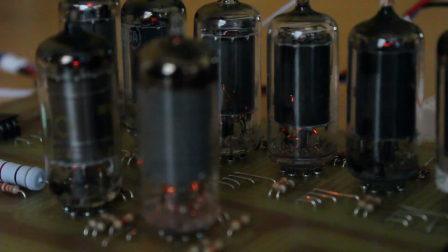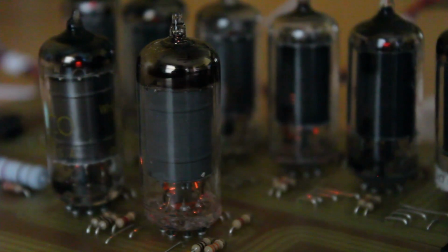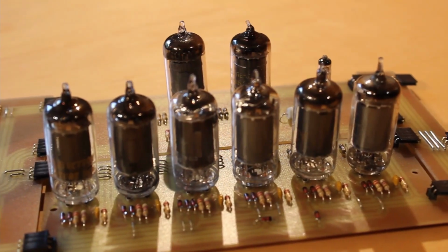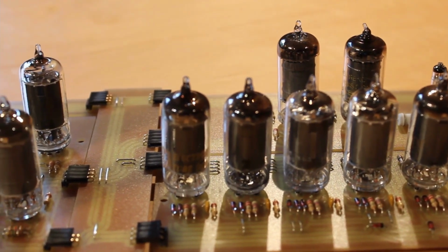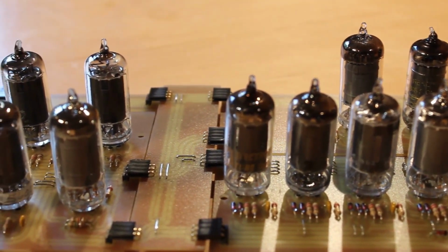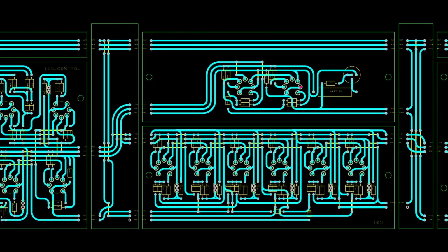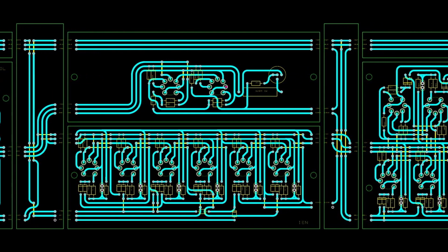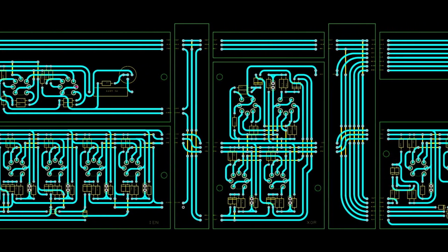You may notice that I decided to test this one by itself. And that's because the instruction register and decoder and all of those boards are now pulling so much power that I'm afraid to add more tubes to it without actually first building a kind of soft start so that our inrush current can be something that we're more prepared to handle. But I want to finish this interconnect board out first, and then we'll get to work on figuring out a soft start system for it.